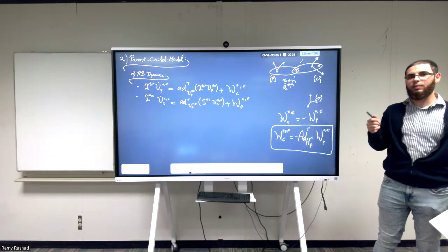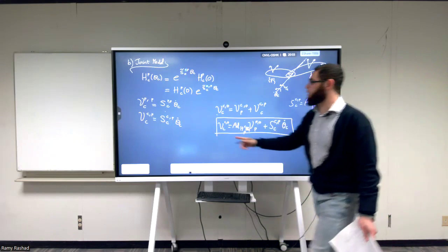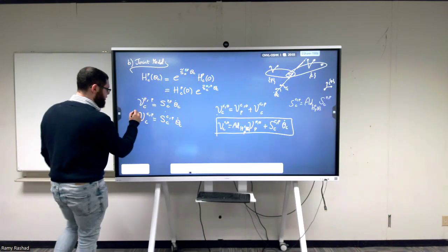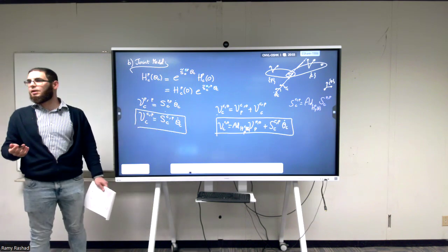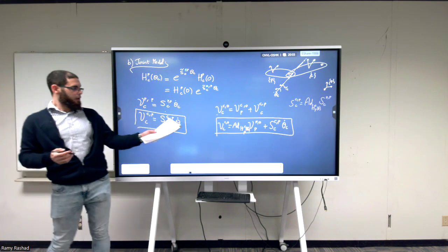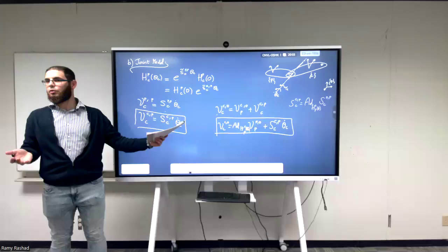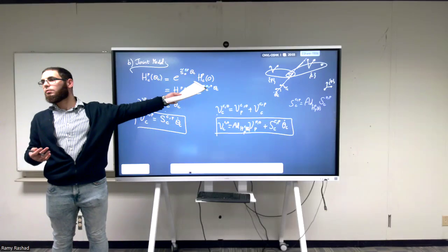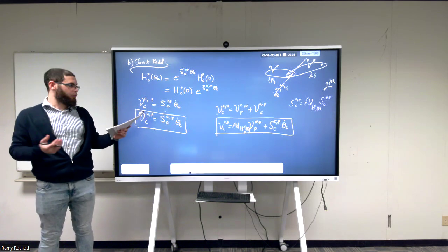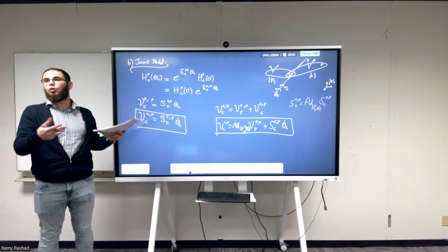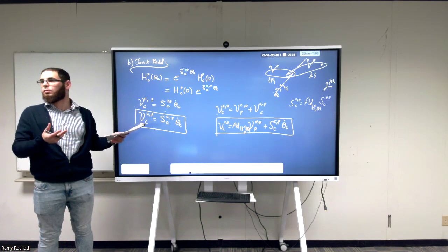It's related to the wrench. How? Now let's look at the duality equation, which is this one. You see this equation? Let's look at its dual. What does duality mean? Duality means that whatever we multiply here by the theta dot to give power, which is in this case the tau. And what is the object that, when we take the duality product with it, with the twist gives us power?